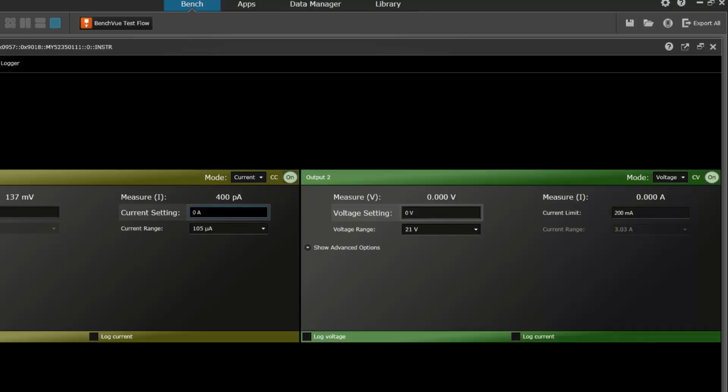Now let's set the base current to 20 microamps. At 0 volts collector voltage, we are reading basically no collector current. Now let's set the collector voltage at 500 millivolts. The collector current has increased now to 4 milliamps. We can repeat this procedure at 40 microamps of base current, manually recording the numbers and eventually plotting the results.